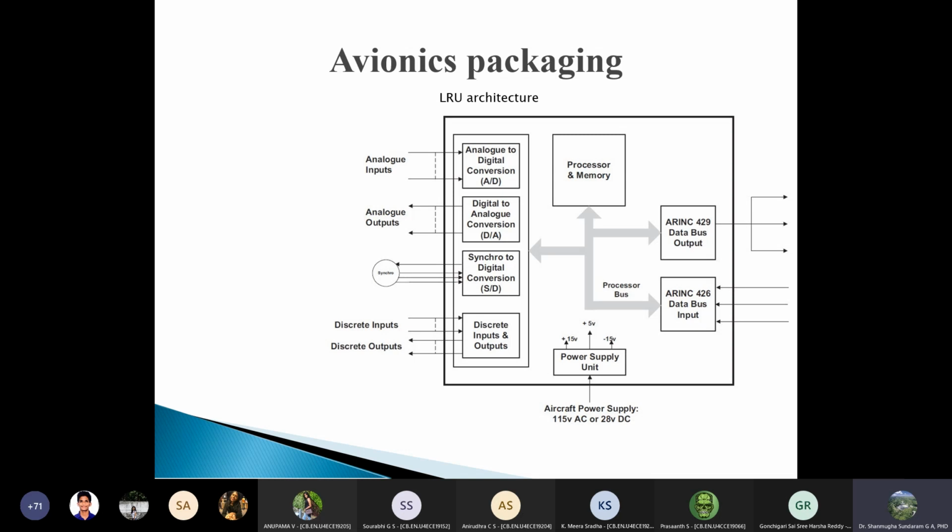Is the monitoring happening at the rate of 10 degrees, or 1 degree steps, or a fraction of a degree? Depending on that, you'll need to convert it into a suitable digital equivalent. As the number of bits increases, the ability to identify smaller changes in angle also becomes possible. So that's the idea of the resolver or the synchro.